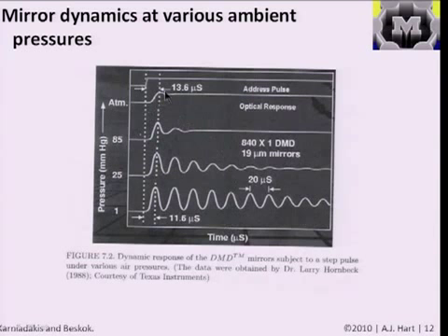But it turns out that at atmosphere, you get a pretty good dynamic response, and the mirror reaches its final position in a much shorter time frame. So now tens of microseconds. And if you're making video at a rate of, say, tens of hertz, then this is quite suitable for that, because you want the mirror to move over and be stable, so you don't see any jittering in the image and can update it frequently.